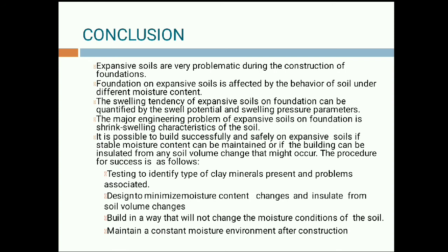The swelling tendency of expansive soil on foundations can be quantified by the swell potential and swelling pressure parameters. Basically, these are the very important parameters to identify expansive soil. First is the swell potential, and second is the swelling pressure.